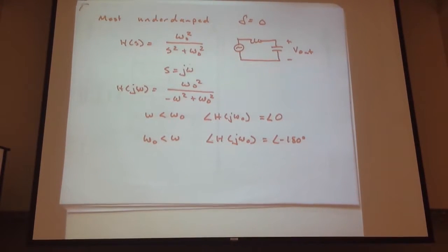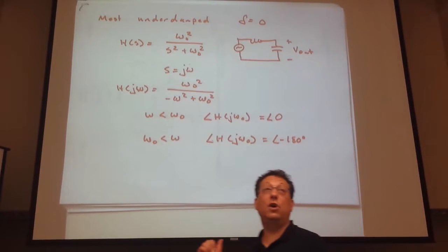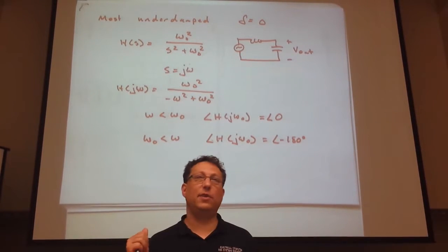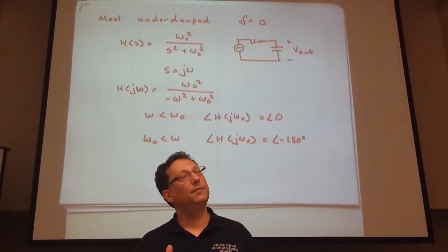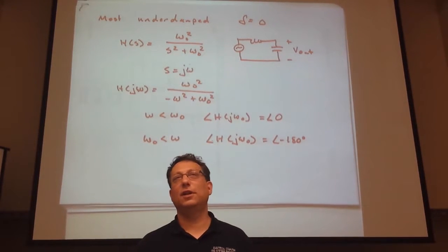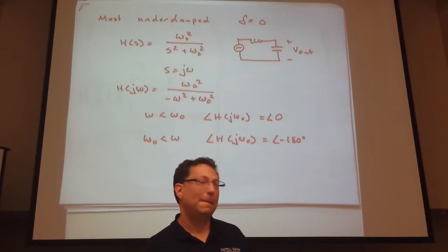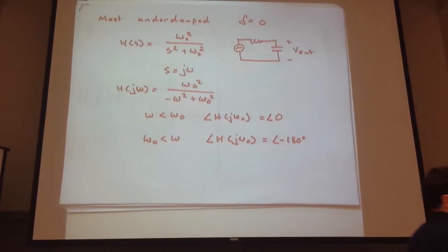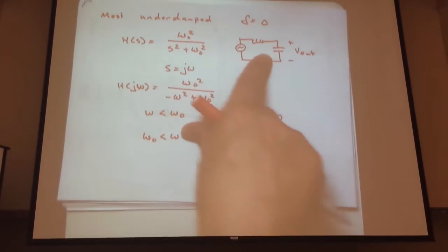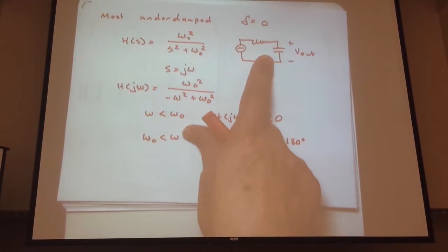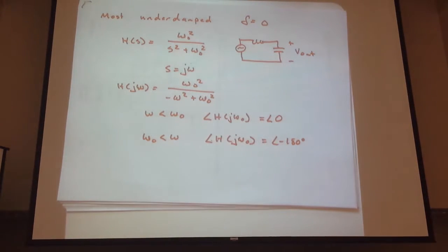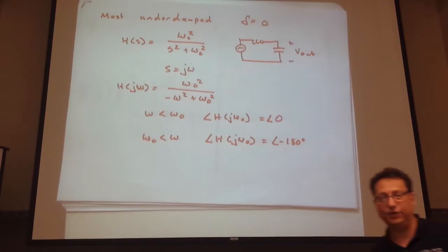Now, practically, what really happens? I mean, you can go on Wednesday and you can build this circuit. I'm not sure it's a good thing for your discovery board, but practically, what will happen? I mean, remember, this is a model. What are we neglecting in this model? Yeah, the wire resistance, the internal resistance of the discovery board itself, which is actually not zero.